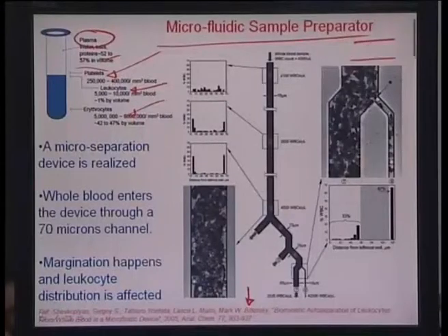So as we have been talking about before, there is a parabolic flow profile which develops in channels which have fixed or static walls on both sides, and the flow within is driven by a pressure gradient, a constant pressure gradient. So let us suppose you have a channel here and you have a parabolic profile like this. So obviously it means that more towards the center the velocity would be more, and there would be a zero velocity or a zero slip on both ends. So therefore from center to side the velocity should continuously reduce, okay.